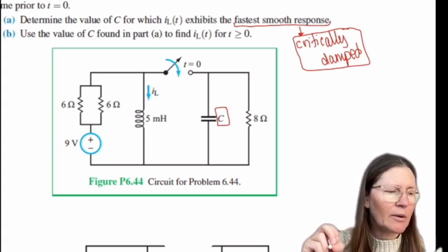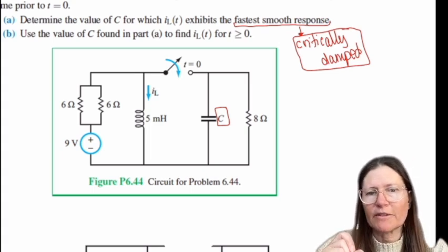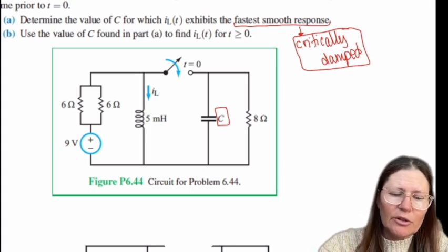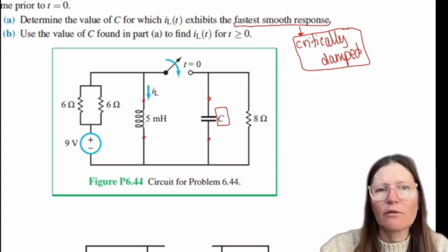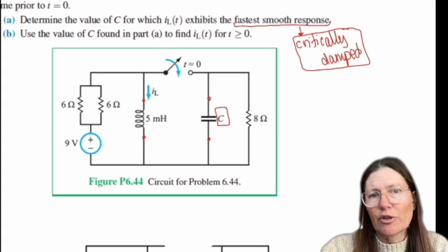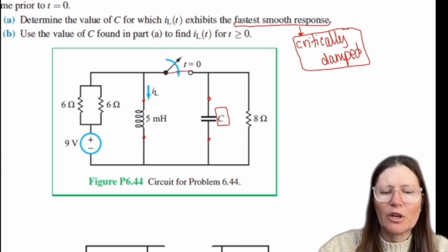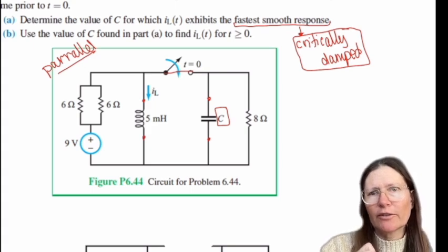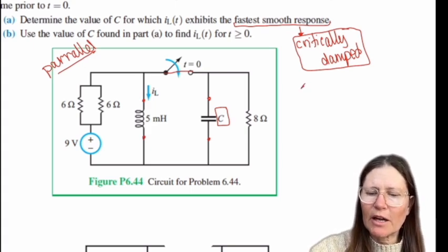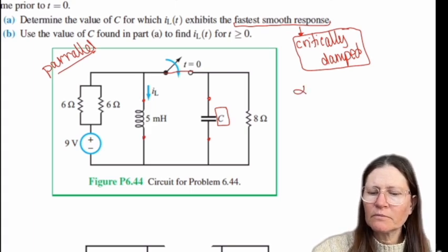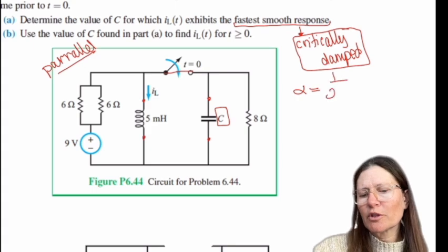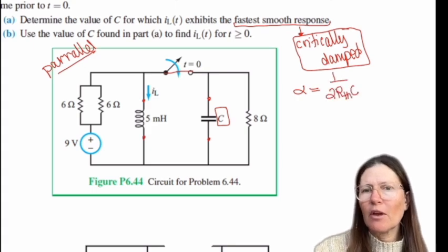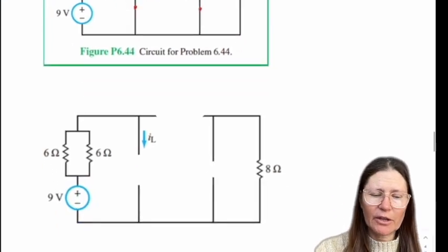And so the table shows us that we need to determine if it's in a parallel or series. So we look at the final circuit and the location of the capacitor and inductor to each other. So here with this closed, you can see that this is going to be a parallel form. So here we have a parallel circuit of LC, and so we can find alpha, which is 1 over 2 the RTHC. So our RTH we find with the final circuit.